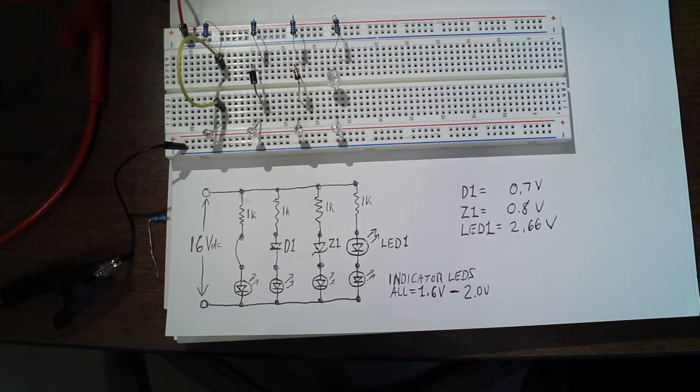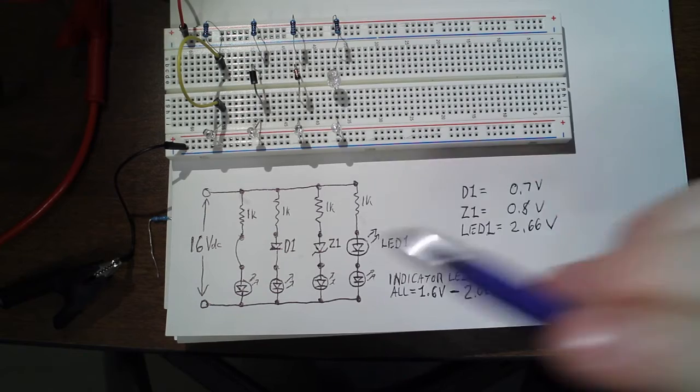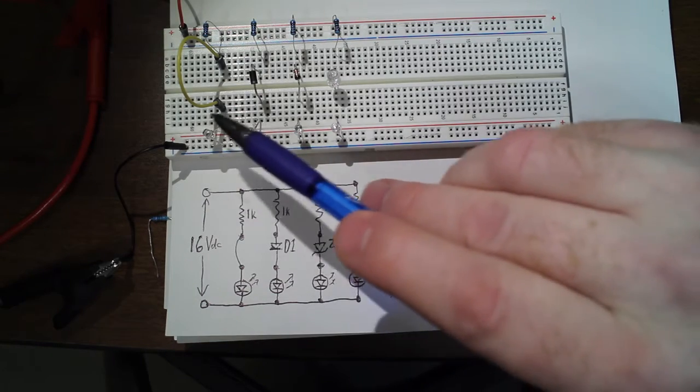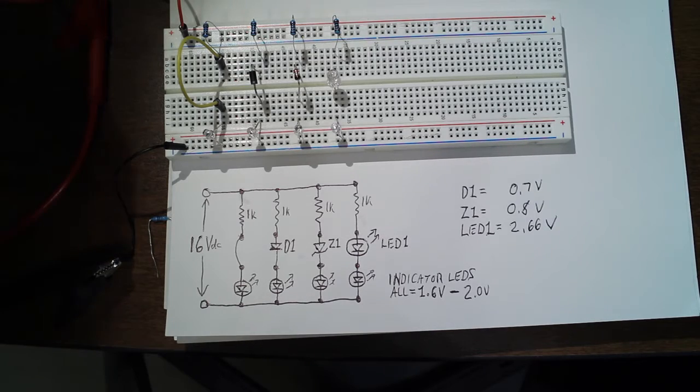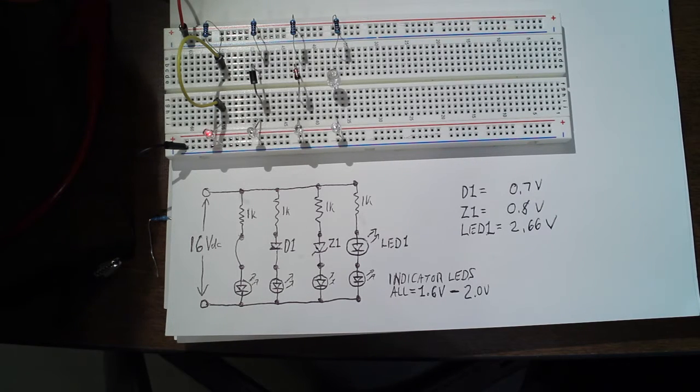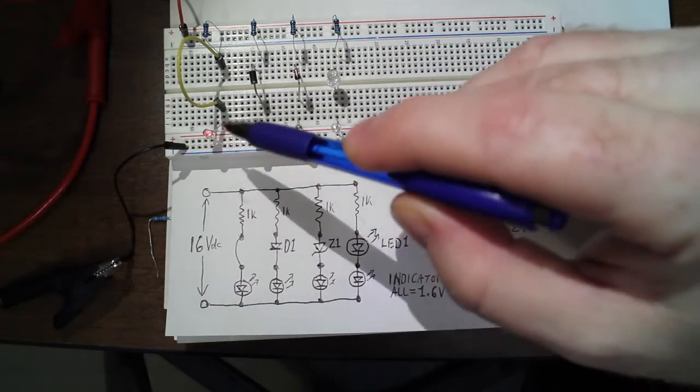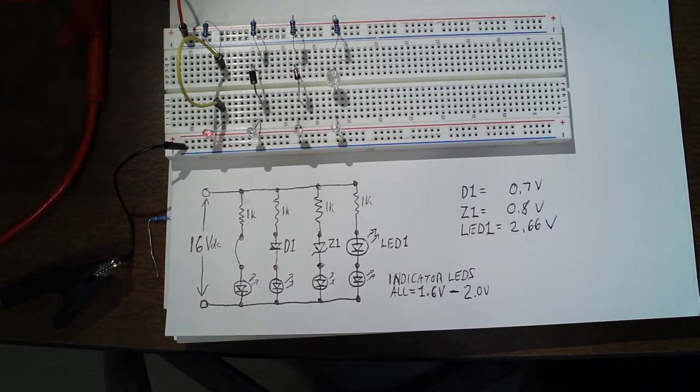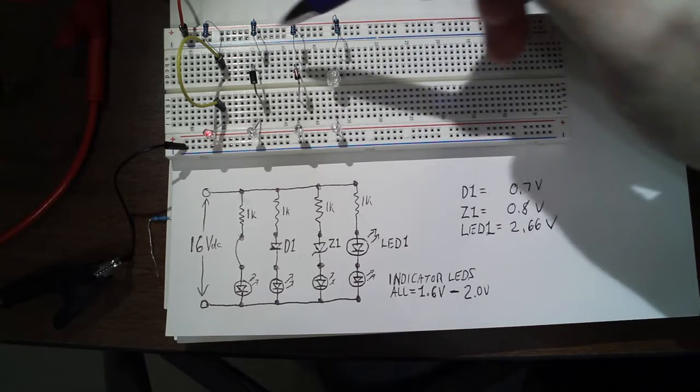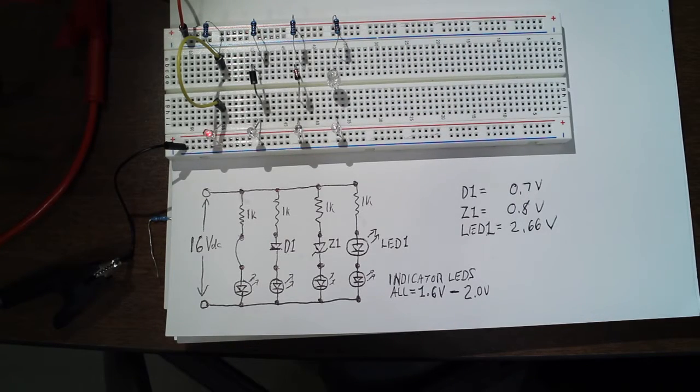So if I turn on the power supply and I ramp it up in 1 volt increments, right now it's at 0 volts. If I go to 1 volt, you will still see nothing light because 1 volt is too low for even the indicator LED by itself. When we reach 2 volts, that's above the indicator LED's minimum voltage of 1.6, so it begins conducting current limited by the 1000 ohm resistance. But the branches with additional diodes in the circuit are still below the sum of the voltage drops required.